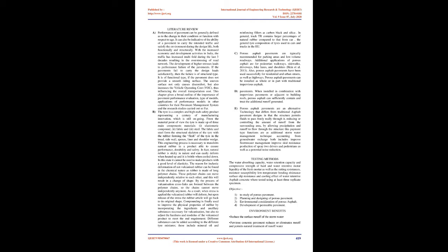The development of higher stresses leads to performance failure of the pavements. If the pavements fail to carry the design loads satisfactorily, then the failure is of structural type. It is of functional type if the pavement does not provide a smooth riding surface. The uneven surface not only causes discomfort but also increases the vehicle operating cost, VOC, thus influencing the overall transportation cost. This chapter gives a broad outline of the importance of pavement performance evaluation, types of models, applications of performance models in other countries for their pavement management systems, and the research studies carried out so far.